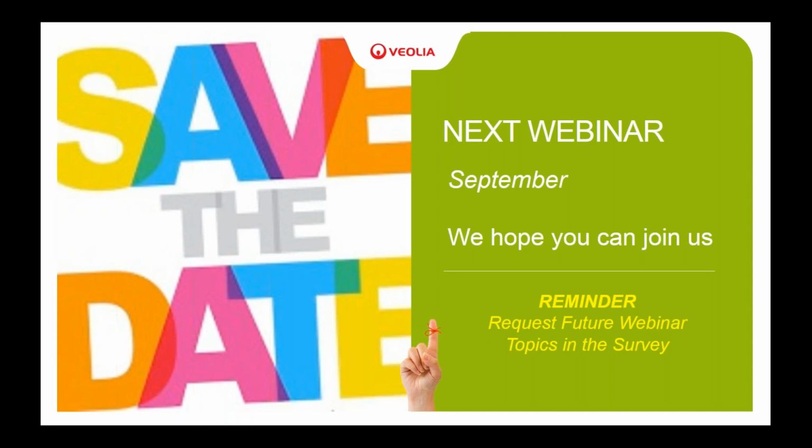For specific things like BOD, just send them out on whatever frequent basis you have. But in the end, yes, you can back off on the testing requirements if your data shows it's pretty repeatable on a day-to-day basis. But we would never say don't do any data collection. Even if everything is repeatable, it's always good to do a couple of measurements at least once a month so you have some back data to understand if something differs from the norm.